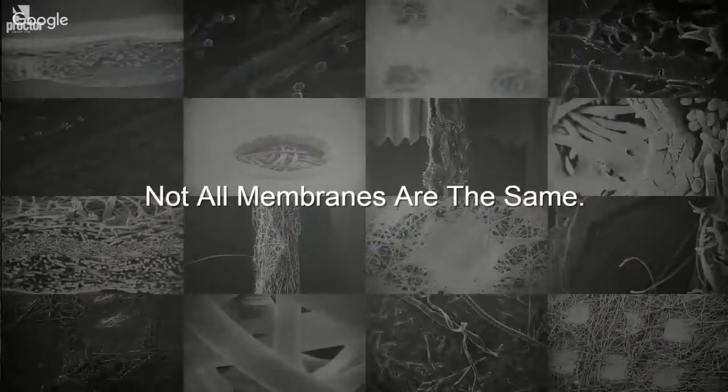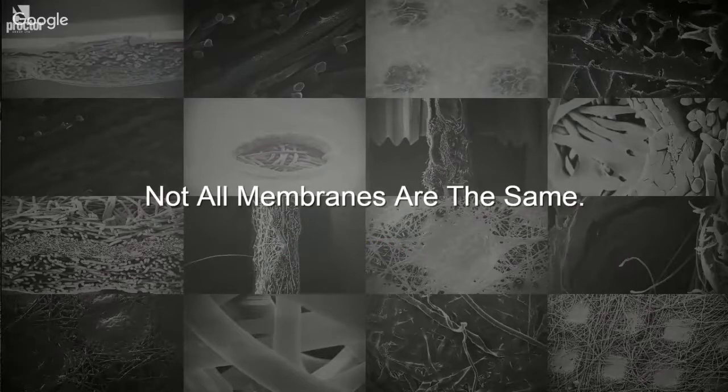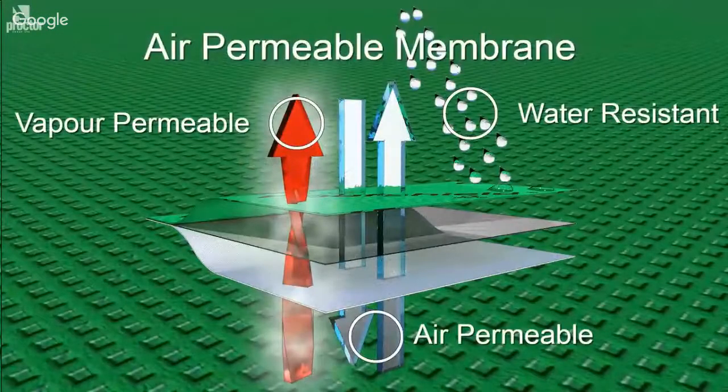So while there's a degree of overlap in the functions of the various types of these membranes, the differences between them are significant, and this of course is going to have an effect on how they're being used. The composition of an air permeable membrane is a core layer of melt-blown polypropylene, which is sandwiched between two layers of spun-bond polypropylene. It's these outer layers that help provide additional water resistance, and they also protect the core from physical damage.